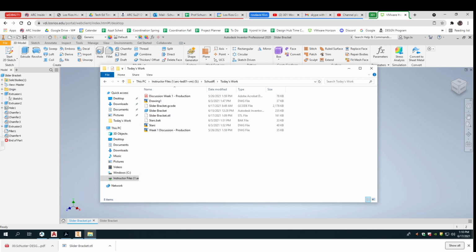And so every time I tell that head to move forward or back and the bed to move right or left, that's actually G code telling it what to do. And the G code also tells that white wire how far to advance, how hot my extruder should be. So there's a code that tells you that. So I need to turn this STL file into G code.